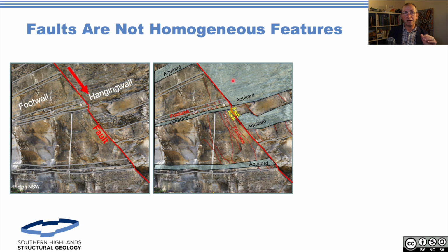So now what I've done is I've marked in my aquifers on the same fault. I've marked in where my fractures are. I've also annotated where I've got fault rock. So what I've done in here is I've described the static structural features that will go into thinking about flow. So these would then be my aquifers between my aquitards. I've got fractures, and that's my base starting point. Now, to conceptualize the flow and start to talk to modelers about how we'd get flow around this, we then come to this static conceptual flow model.